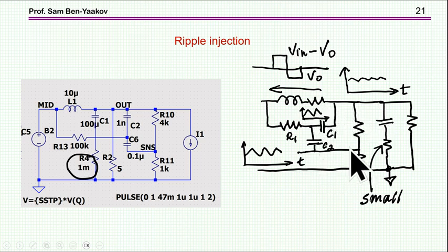There is another way to look at it, which I think is very important to understand, and that is that this arrangement is really emulating the current of the inductor. You might say that this R1, C1 is an emulator of the inductor current, because we have this voltage across this network here, and the voltage across the capacitor is in fact emulating the current through the inductor.